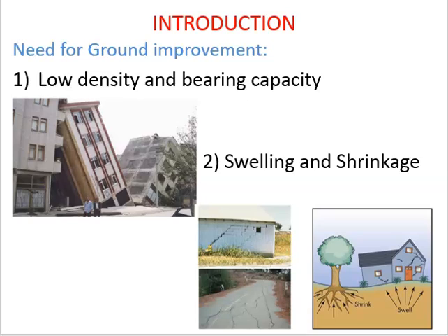These smectite clays swell excessively during rainy season and shrink on drying. This exerts uplift pressure on the buildings. If the structure is lightweight structure, it will get uplifted and causes failure. If it is a heavy structure, then also it causes cracks in the walls. If it is a subgrade soil, even the pavements get cracked. The underground piping system also gets damaged due to these swelling pressures.